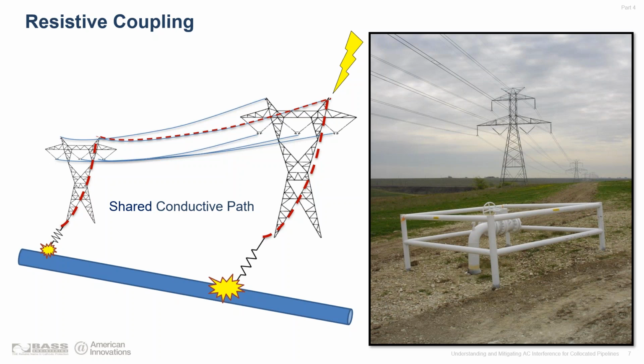So what do you do to prevent this? You can't really prevent it, but you can at least take the proper precautions to make sure that everyone is safe whenever they're working on the pipelines. Clay, in our second presentation, talks about the mitigation tools available. One of them is those gradient control mats. And setting up those things on any type of asset that an operator is going to be working on is crucial, because then you'll mitigate the chance for any step-touch potentials, which can lead to a shock hazard to any personnel.